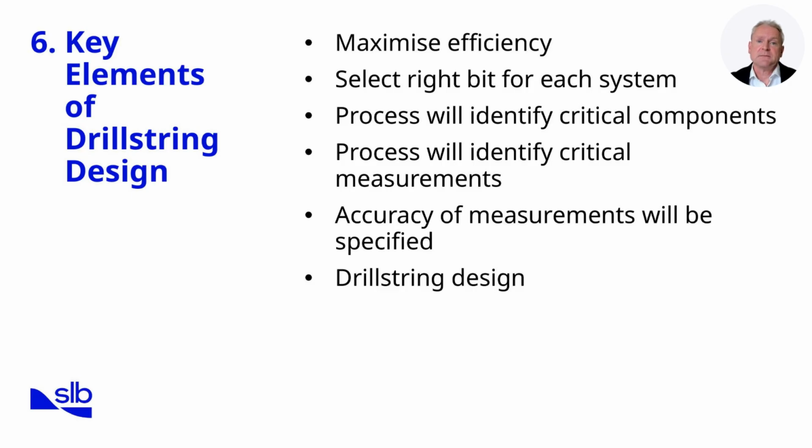or conventional assembly. The design process then identifies critical components in the string, such as heavyweight drill pipe, stabilizers, and jars, which directly affect torque, drag, and load transfer. Alongside components, we must define critical measurements, including weight on bit, torque, and bending stresses. These values are used to assess mechanical limits.